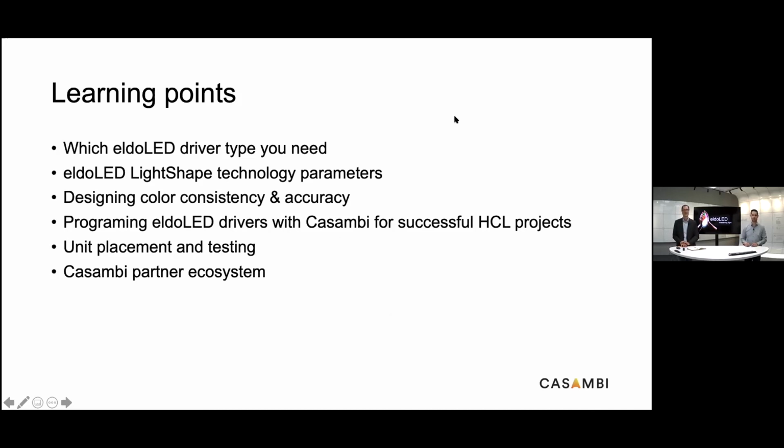So Christian, maybe you can point out the last two bullets on the slide from a learning perspective. Yeah, just to recap what I mentioned, obviously it's a radio frequency that we're using here with Casambi. It's Bluetooth Low Energy, it's 2.4 gigahertz, and the surroundings do affect the range. It's a mesh network, so you really want to ensure appropriate testing. We have multiple documentation available for that online. When you do go through that process, we'll ensure that we've got the support for you to make sure how you can optimize it or what considerations need to be in place there.